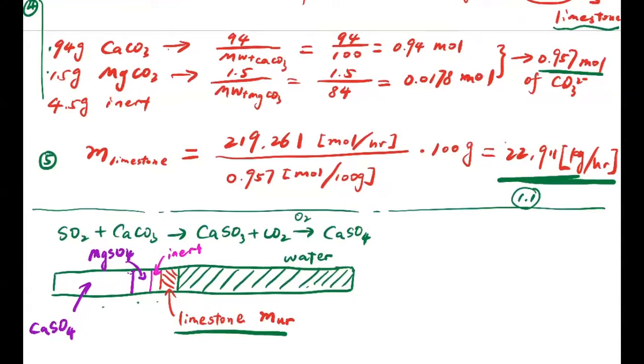The unreacted limestone is going to be 22911 multiplied by 0.1 divided by 1.1. Among this 1.1 total amount of limestone, basically 1 is being reacted in this process, and 0.1 is just extra, right? So this is going to be the unreacted fraction of the limestone, and you can find that this amount is 2083 kilogram per hour.